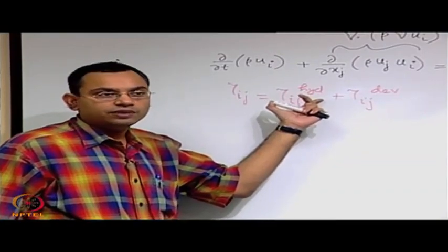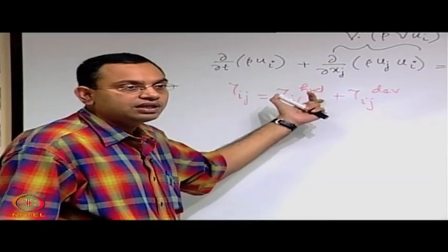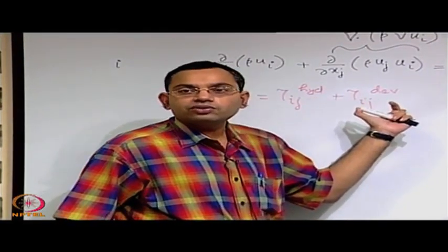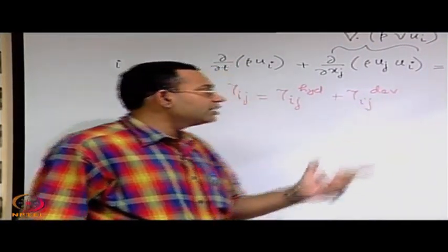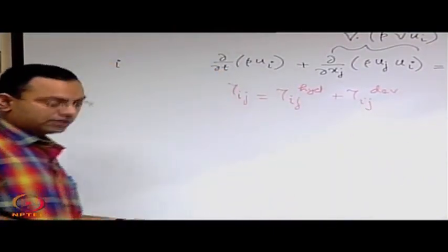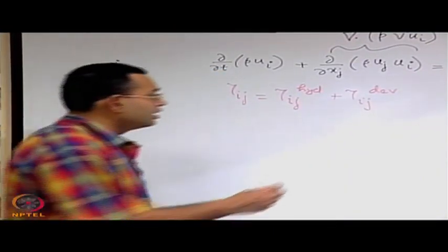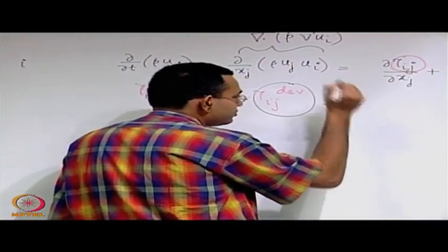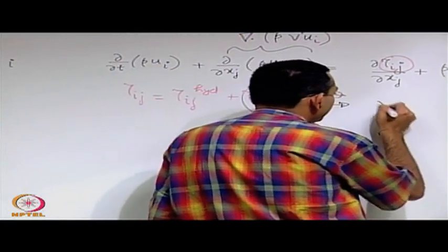It does not mean that when the fluid is in motion it is not there, it is definitely there, but something additional is there which is attributed to the deformation of the fluid, and we figured out how we relate that with the rate of deformation. So we related this deviatory stress component with the rate of deformation by this one,